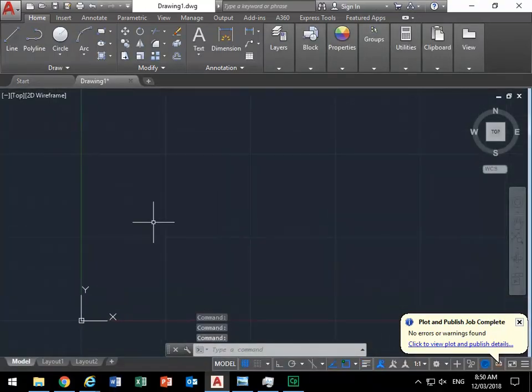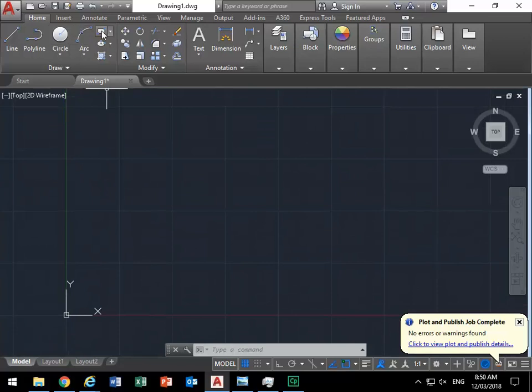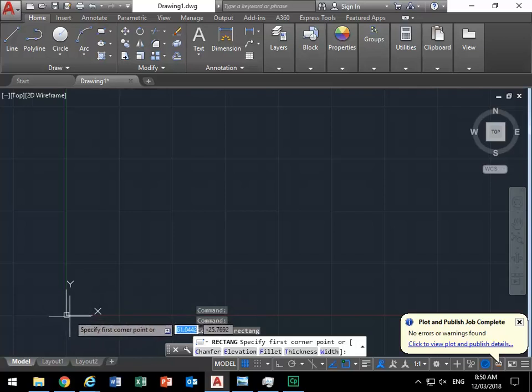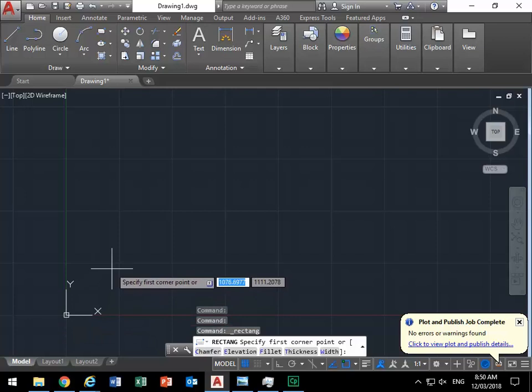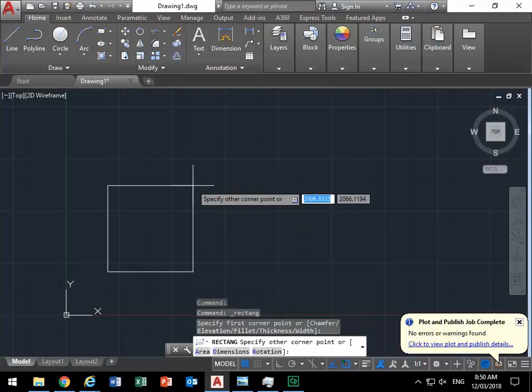And then I'll begin by drawing something to set out my building first before I even go to make any layers. So using the rectangle tool, I'm going to give a point that's just above and to the right of the origin. Sometimes people begin on the origin, but in this case I want to leave a bit of room and set my start point out from that corner. So I'm just going to click a point there that you can see is inside this XY plane, and use that as my start point, and then type in the overall size of this building, which is